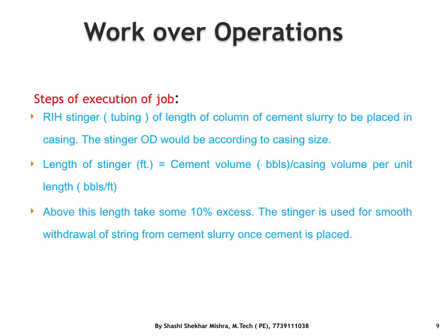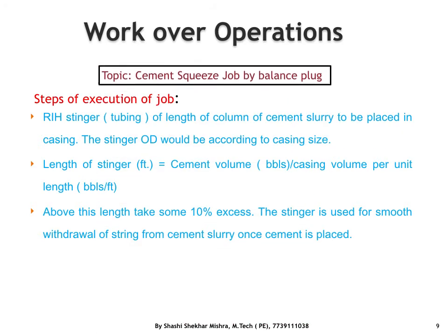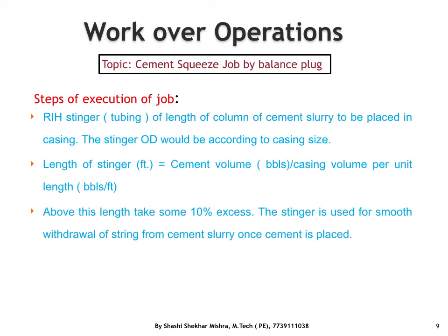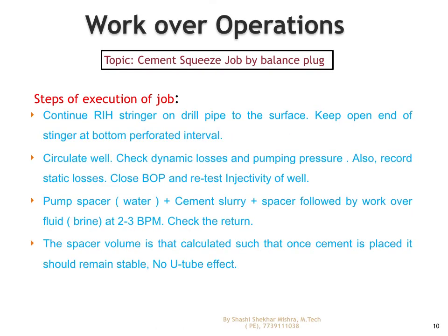Now once it is placed, circulate the well, check for dynamic losses and pumping pressure, and also record the static loss.